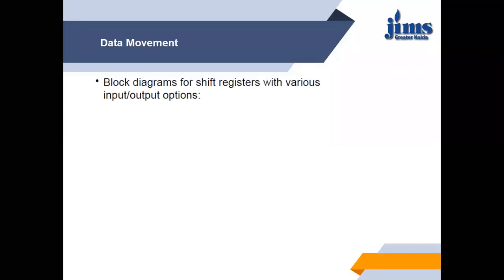The block diagram of the shift register with various inputs and output options. So here, in the last slide, we have just shown the input and the output. So here will be serial in, serial out. We have a preset control, we have a clear control, and we have a shift pulse. Shift pulse is nothing but your clock.